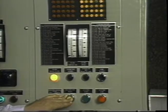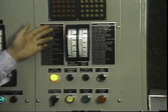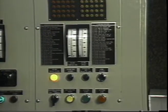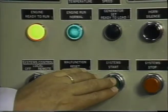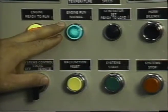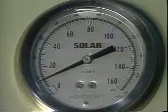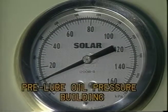When I release the same push button switch, the malfunction and alarm lights extinguish and the engine ready to run light remains on. At this point, nothing else will occur until the start switch is pressed and released. When that happens, the green engine run normal light will come on, assuring that the start sequence has begun. Simultaneously, the auxiliary prelude pump will turn on and oil pressure will begin to build.